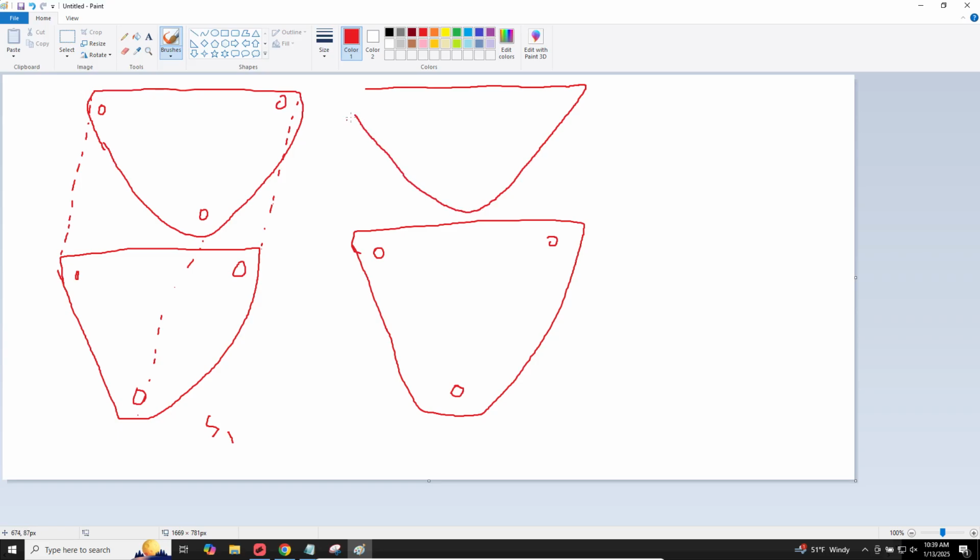But for this top left-hand corner, there's a problem. There's a missing piece, if you will. This is where there is a hole. So now there's a problem for the hex mesher. Here, it can extrude the elements from this point to that point. For this bottom point, it can extrude the elements from this point to this point. But for this top left-hand corner, where is it going to extrude the elements to? That's a big question mark for us.